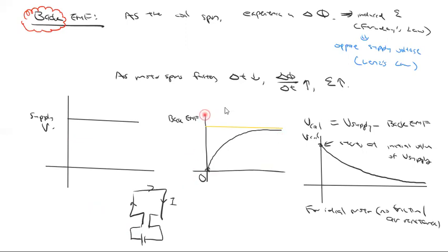As this spins up, your back EMF is going to increase. So the voltage across the coil, literally if you had a voltage measuring here and here, is going to drop because of the back EMF. Conceptually, the back EMF is kind of like a battery that gets stronger the faster it spins. So these two batteries are going to fight each other, is what I'm basically saying.